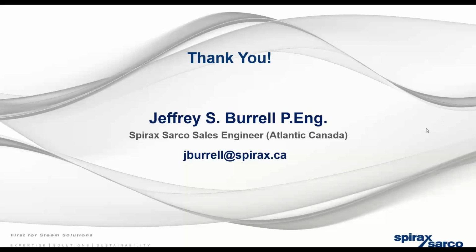Any other questions? Can you use a spring check valve in a steam system? I'm not sure... Yeah, no, I can answer this. Yes, if you're going to use a spring check valve, a lot of questions need to be asked. How big is the condensate line? How big is the check valve? Those types of questions. But as long as you're using all stainless steel components so they don't rust together over the summer, you should be okay.